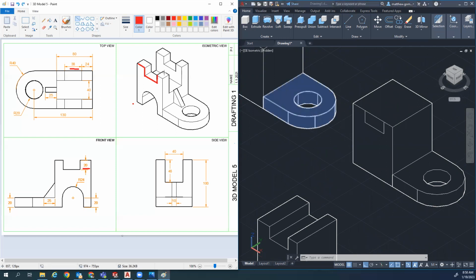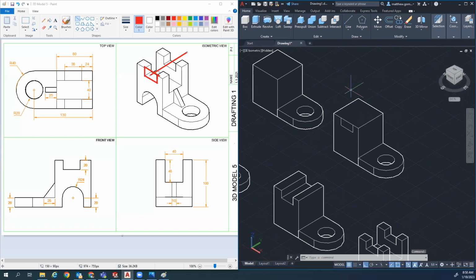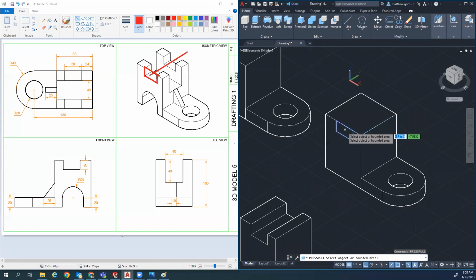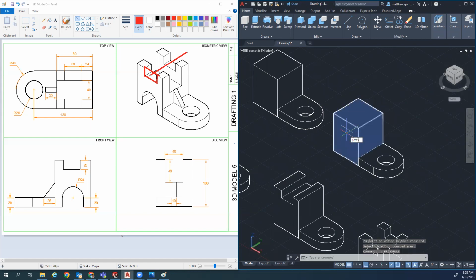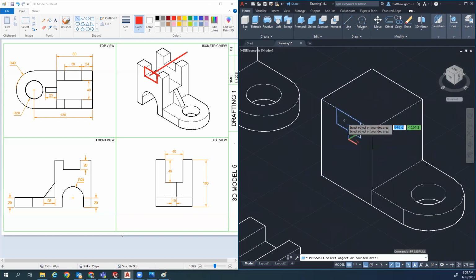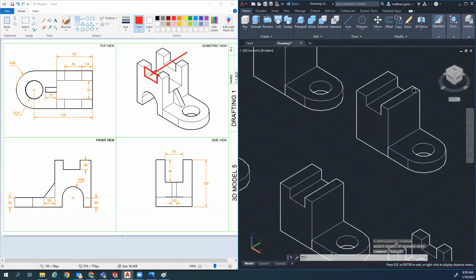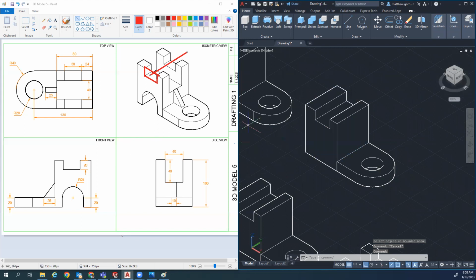Just imagine this box up here, and then we're going to press pull it that direction to erase or cut away from this big piece. So I'm going to use press pull, and whenever you're trying to remove mass from something, don't click on the shape itself, because if you click on the shape, well, it works. Imagine that. But anyway, I usually try and click on the inside face of the shape like that, and then press pull it back, because that works the majority of the time. So you just create that box, press pull it back.